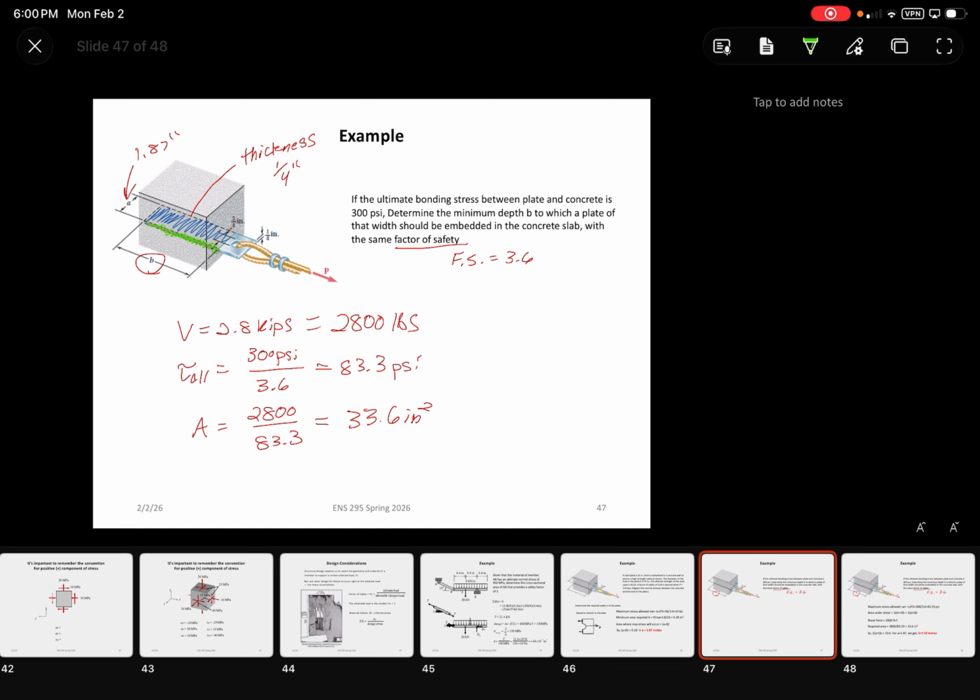So now what we need to know is the value of that area. That area we can write as A times B, and obviously there's two of those, top and bottom, plus the thickness of the plate times B, BT, and then it's reflected on two sides. So this can be rewritten as 2B times (A plus T), which we already know what B and T are. A we calculated as that 1.87 inches, right? And then T was the 1/4 inch.